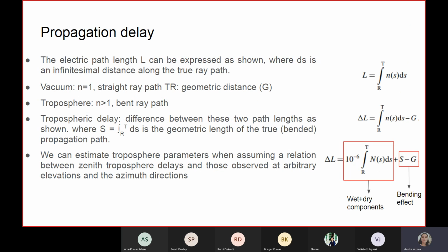So we are talking about the error caused by the propagation of the signal. How is this error popping up? It is popping up in the delay measurement. What is delay? The signal is coming from the satellite to the receiver, but it is getting delayed. It should have arrived earlier than the time it has arrived. Since it arrives at the receiver a little late, it has traveled a little more distance than it was supposed to. That little extra distance is represented by tropospheric delay, ionospheric delay, or atmospheric delay.